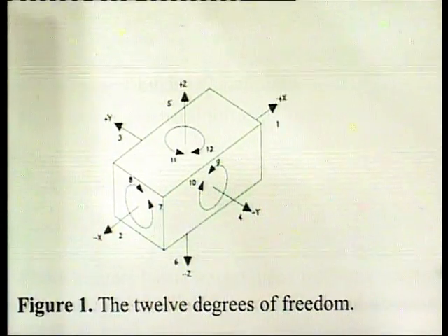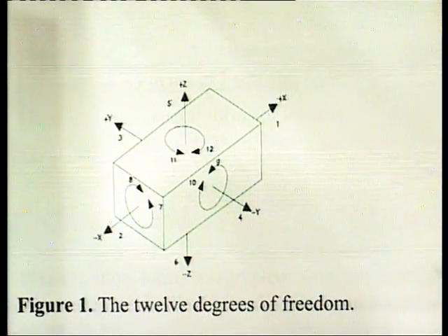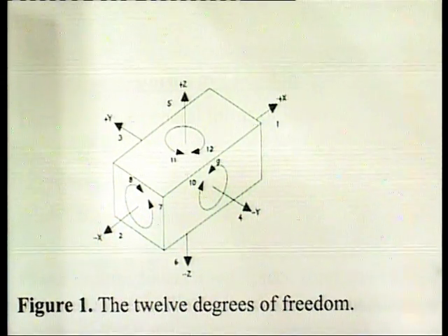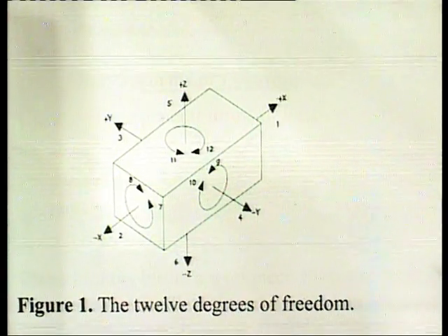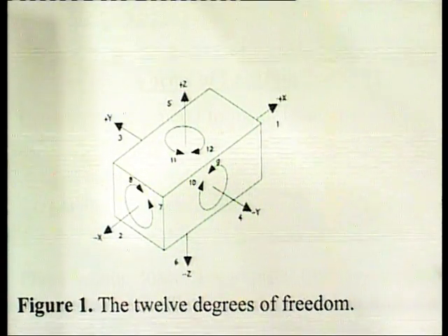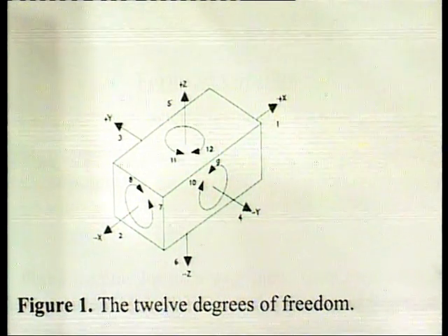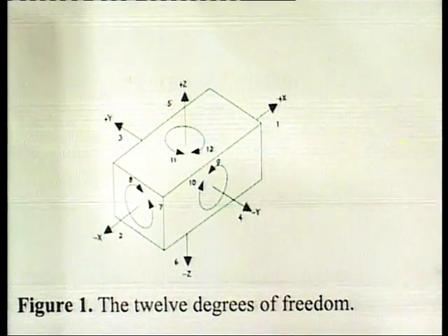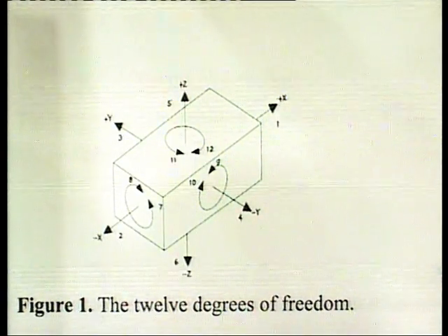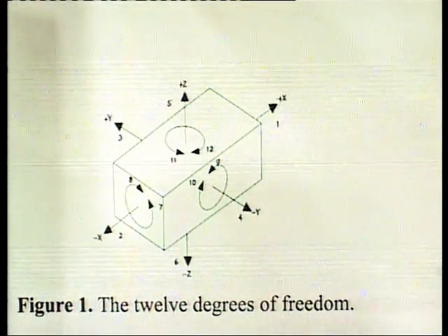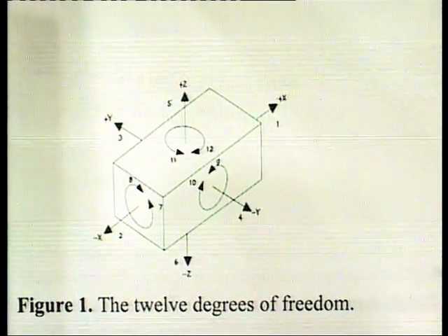This fact also points out a crucial element in work holder design. Locators, not clamps, must hold the workpiece against the cutting forces. Locators provide a positive stop for the workpiece placed against the stop.